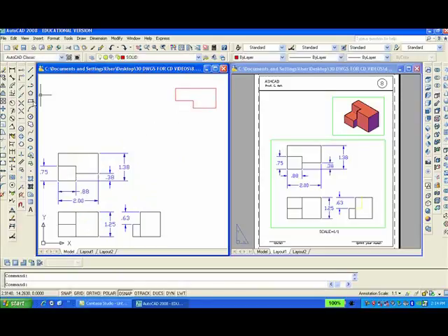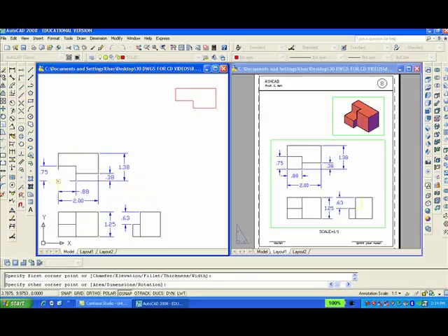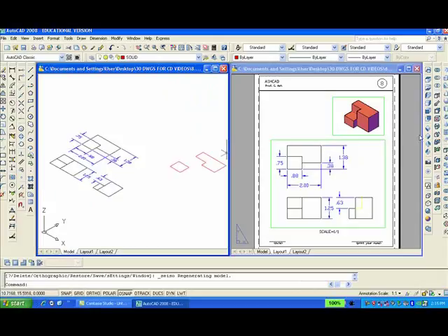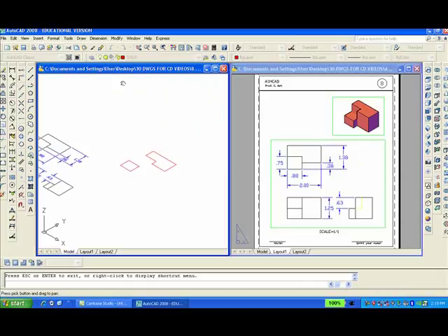Now I want to do the rectangle, 2 opposite points like that. M, enter, L, enter. Select that and move that up. And I can go into southeast isometric, and I can pan over here like this, zoom with the window like that.